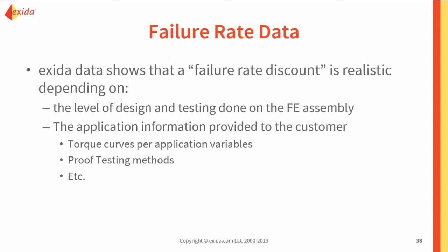So, as I said a little bit earlier, if you're doing the things we talked about in that integrated design, the engineering calculations, the torque curves, and you're doing what proof testing should be done for the final element assembly, there can be a failure rate discount, and it can be realistic depending on how far you are going with your integrated assembly.